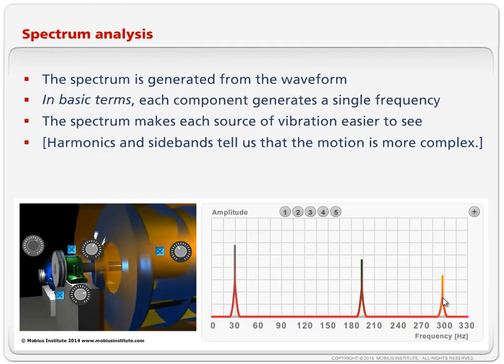So if someone talks about vibration frequency, you might hear them say, oh, it was the 10x peak. What's the 10x peak? Well, the 10x peak is 10 times the running speed. And a vibration analyst might think, oh, I wonder if there were 10 blades in that fan or 10 vanes in that pump. That's the sort of thing.